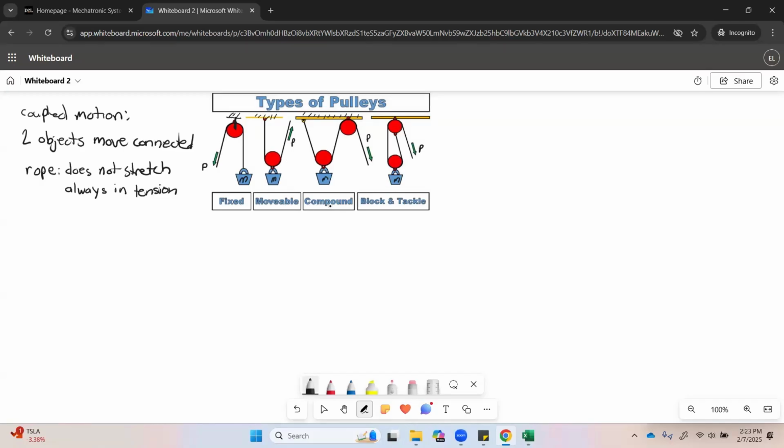Now, what I was saying as far as how to work the pulley problems, the easiest way is to count the ropes. So a typical pulley problem will ask you either for the mechanical advantage, which is going to be some ratio of pulling force to object force, or object speed to pulling speed. Now, we're still in particle kinematics, so we haven't added in forces yet.